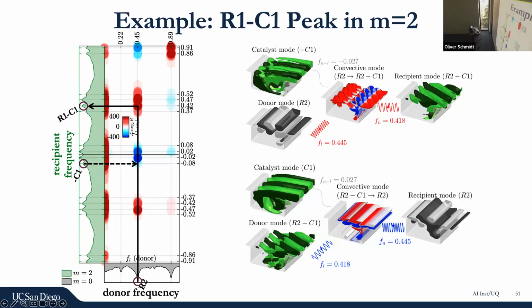So we see the slow roller interacting with this Rossiter Kelvin-Helmholtz type instability through this very complicated flow field to pump energy from the Rossiter into structures that have this small inclination angle. That's interesting because there are tons of papers where people describe the slowly meandering behavior of these waves, and this is exactly the explanation. The nonlinearity creates these oblique waves that then slowly vary their phases, leading to these meandering, snaking structures.